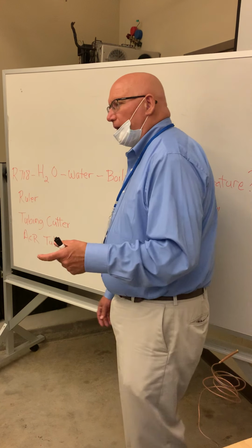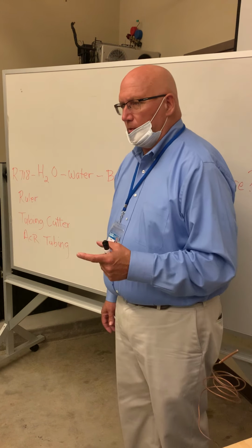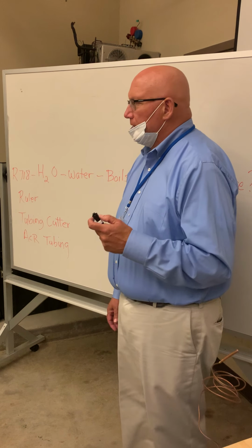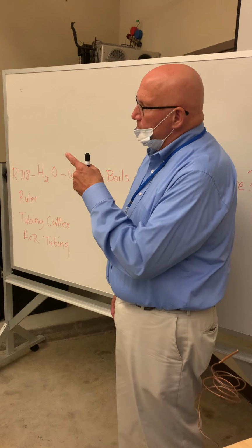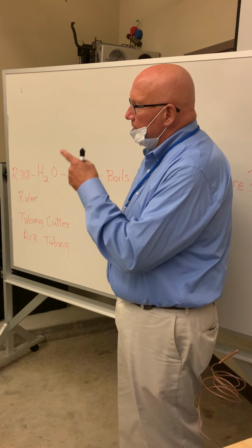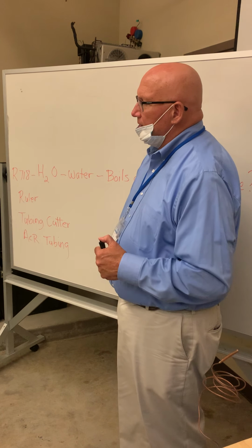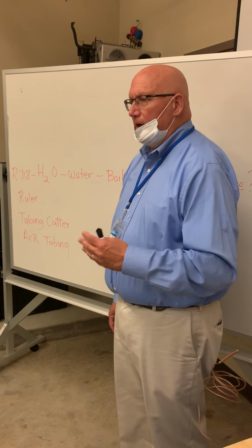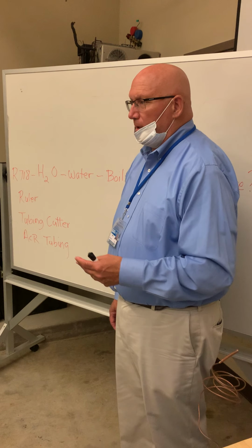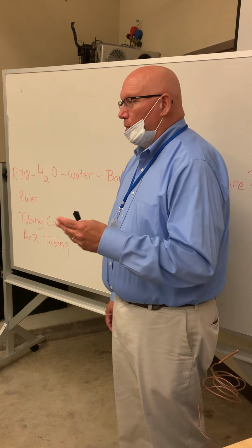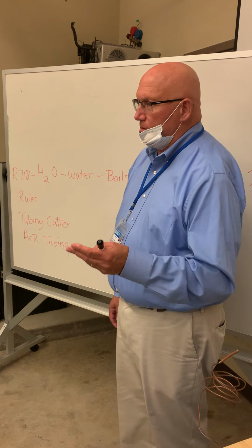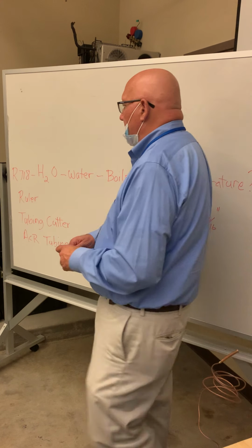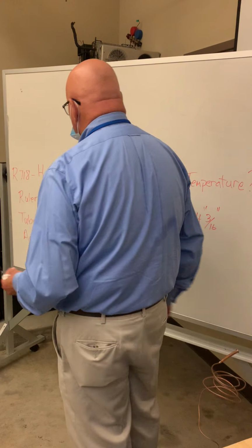So electric shock, that's what you've got to watch out for. The reason why you get an electric shock, this one is mitigated somewhat because you see that the legs of the ladder are made of fiberglass, a non-conductor of electricity. But what if it's a metal ladder, which you shouldn't use for electric, but that may be what they have out there? So what happens in electric?